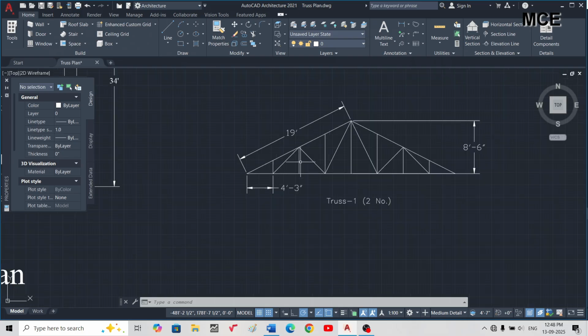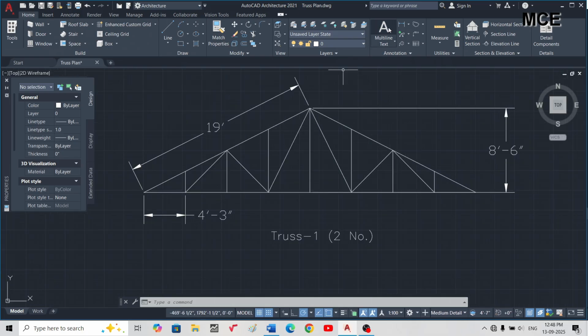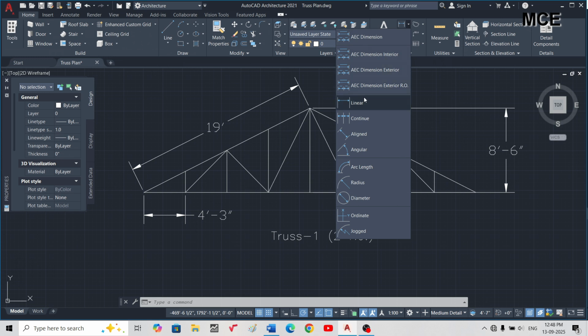Here in my case the snow loading is not much, so I will take less weight sections. I will take angle sections for my rafters and bottom chord.